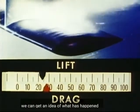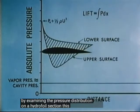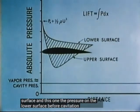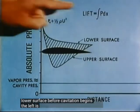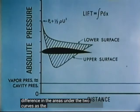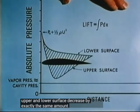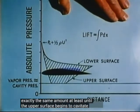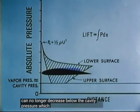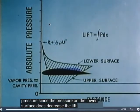We can get an idea of what has happened by examining the pressure distribution on a hydrofoil section. This curve represents the pressure on the upper surface, and this one, the pressure on the lower surface, before cavitation begins. The lift is proportional to the difference in the areas under the two curves. As the ambient pressure decreases by a certain amount, the pressures on the upper and lower surface decrease by exactly the same amount, at least until the upper surface begins to cavitate. At this point, the upper surface pressure can no longer decrease below the cavity pressure, which is near the vapor pressure. Since the pressure on the lower surface does decrease, the lift drops.